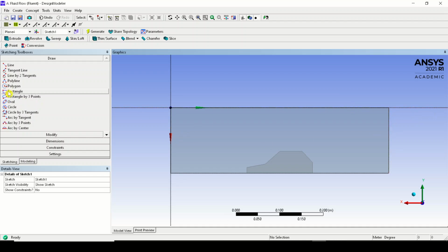Okay, and you can see the simplifications in the CFD model. In reality the window will be a complete solid model, but for CFD simulations it is not really desired for us to create a solid geometry in that form. So we can just play with the faces; we just have to rename the faces and assign the appropriate boundary type. That is more important in CFD, right?